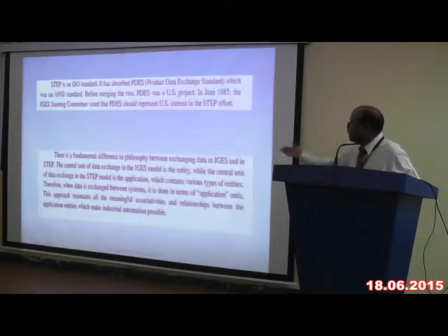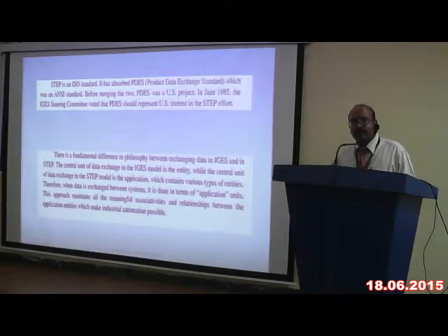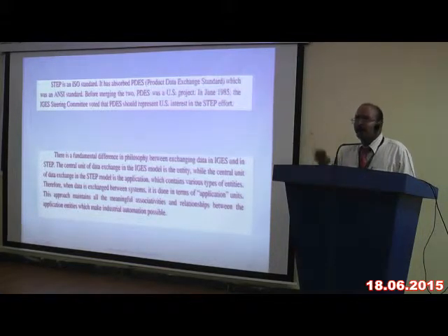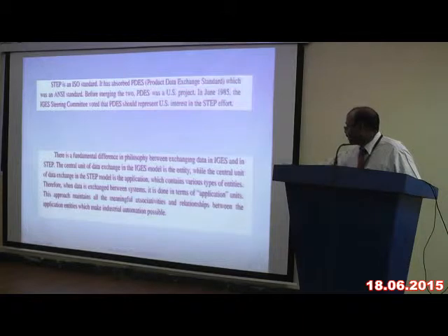And what is this? The difference between two platforms, two formats. What about IGS and what about STEP? STEP is nothing but your indirect translator, and IGS is nothing but a direct translator. I think you know the difference between direct translator and indirect translator. So which is the best? Indirect translator is the best. You are bringing a neutral file and you are exchanging the data between two systems, system 1 and system 2. So that is the main one.